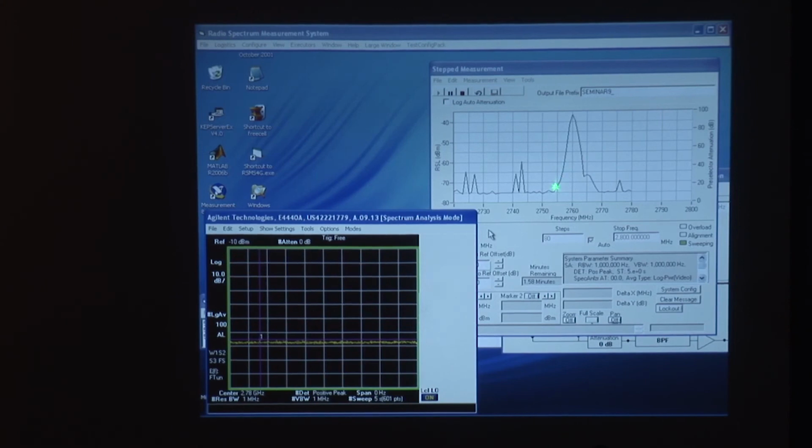You notice that the way that it fills in the radar spectrum, we don't get any gaps. You will typically, with a positive peak detector running in maximum hold mode, get little gaps through here. That doesn't happen with a stepped algorithm because we methodically wait at each frequency for the radar to look at us. As I said, these points are not the radar emission.